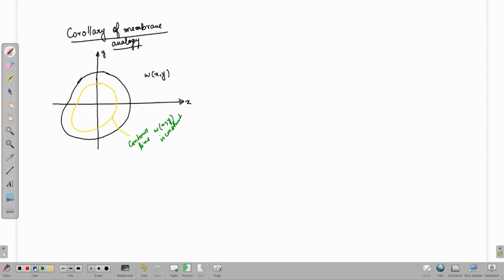So, let me put it in other words. Suppose I select a point P on the contour line. Now, at point P, I will have two shear stresses. One would be tau x z as we have seen earlier, and one will be tau y z.